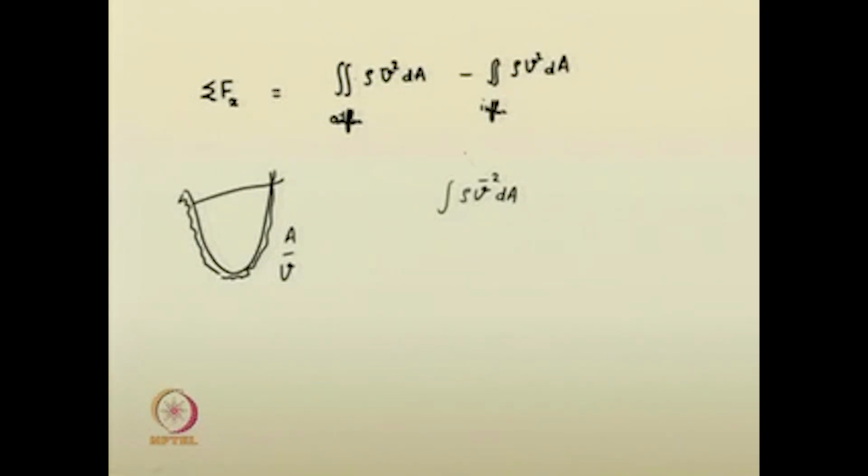So, the areal integral, one can now write this quantity, because rho v squared dA, you know that this is not the average velocity, this is only the velocity at any point in the section. So, this quantity now can be represented in the form of average velocity v squared into A, but they are